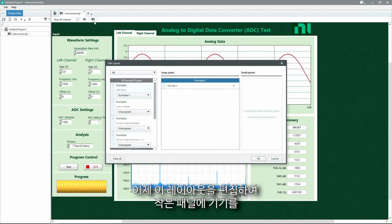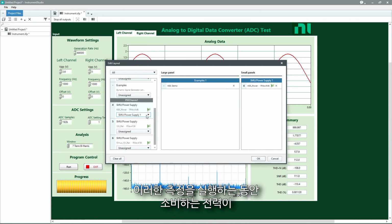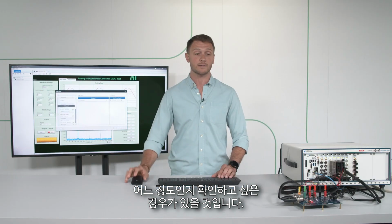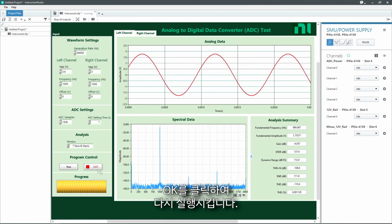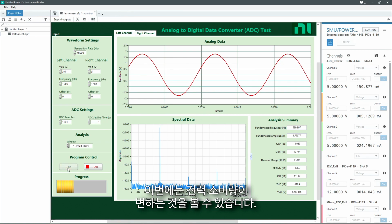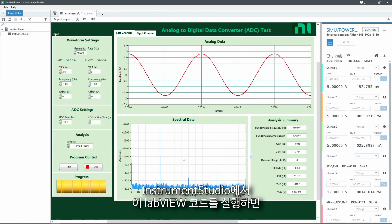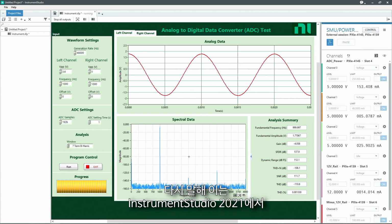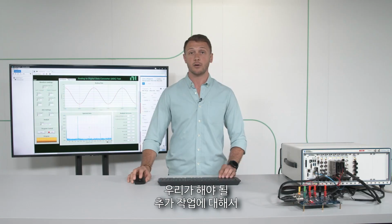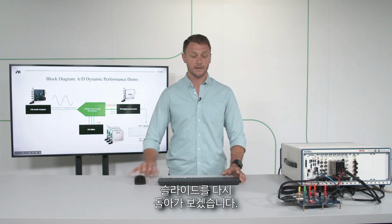What we'll do now is we'll edit this layout to show you how you could easily add instruments into a small panel. So maybe we want to see how much power this part is consuming while we run these measurements. So I'm going to add my SMU channels on the right-hand side, click OK, and I'll run it again. This time around, you'll see the power draw change. We're using pretty basic 5 and 12 volt rails, but you can see the power change on the SMU as we run this LabVIEW code in Instrument Studio. So again, this is available today as a part of Instrument Studio 2021. Now, there's additional things that we're going to do to improve this experience for you, and that's what we'll talk about next. We'll switch back over to the slides.